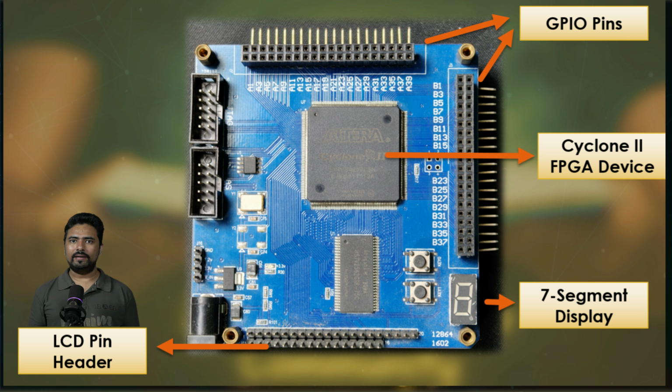By using the assignment editor, you can influence how a specific section of your code or design is implemented in the hardware. This optimization can lead to better overall design efficiency. Understanding how to test a complex FPGA design is very crucial. We will cover how to perform simulations using ModelSim, including developing comprehensive test benches, especially for the